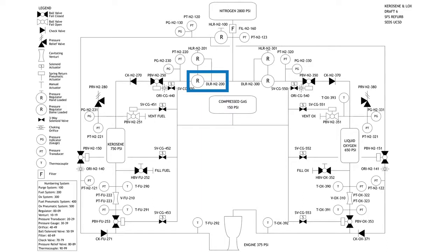So someone's going to be literally sitting on the system, and they're going to start at 5 psi, turn it once, go to 10 psi, and go all the way up until they hit 750. Once they hit 750, that dome is going to know that no matter what pressure I get, because you put 750 into the top of my head, whatever comes through my bottom has to be 750.